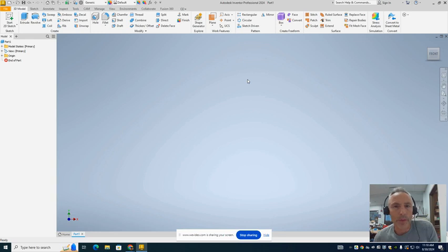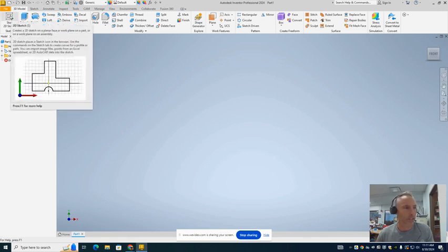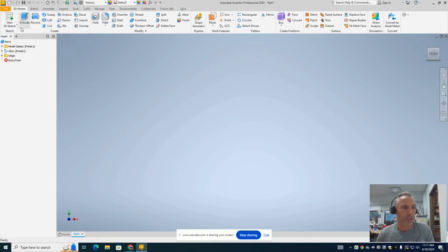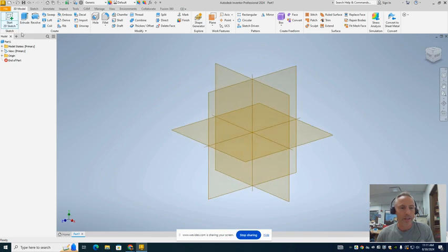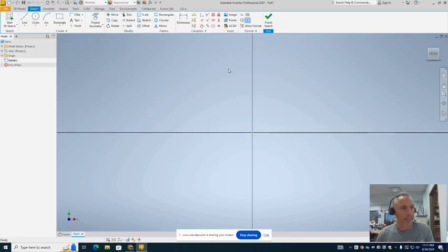And now I'm going to walk you through the actual creation of the train body. The first thing we're going to start with is a sketch. It's a 2D sketch. You will see that there are options for 3D sketch also if you click in here, but we're not going to use 3D sketch at this point. We're going to use the 2D sketch. It's going to offer you the 3 standard planes: your front plane, your right side plane, and your top plane. For the train body, I usually design it from this front plane, which is the XY plane. Now, if you choose one of the other planes, it's not a big deal, because you'll be able to reorient it in the assembly. So I'm going to click on that, and it's going to look directly at it.